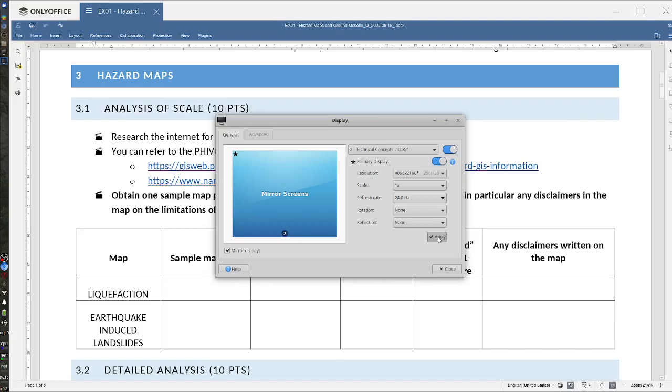Okay, so generally for big projects or for planning stages of projects, hazard maps are useful. Okay, if you're just doing a general planning. But once you start dealing with actual hazards, for example, liquefaction. Okay. Liquefaction usually involves alluvial deposits, particularly the silty or the sandy ones.